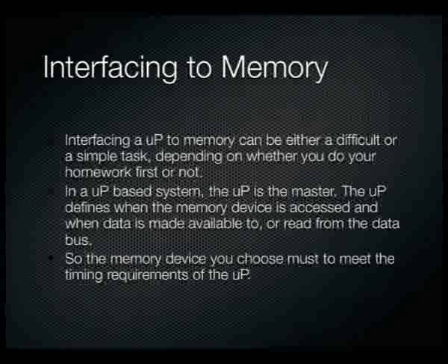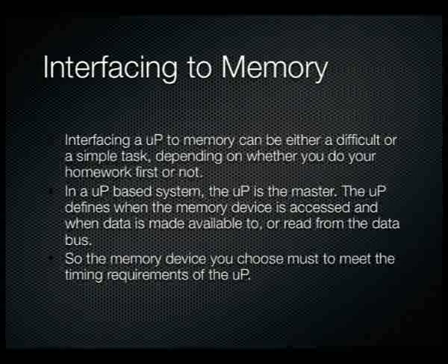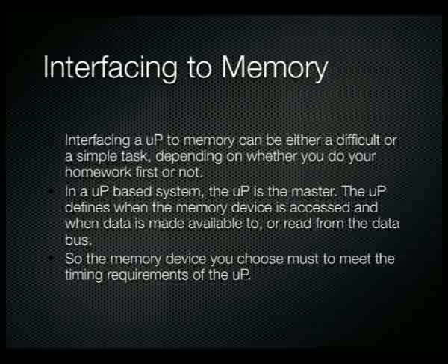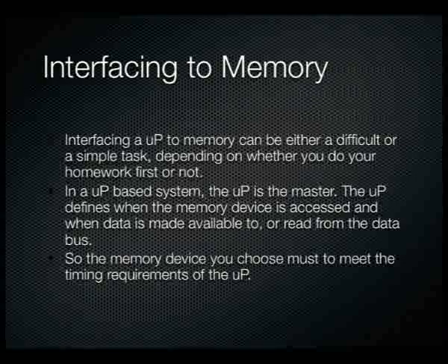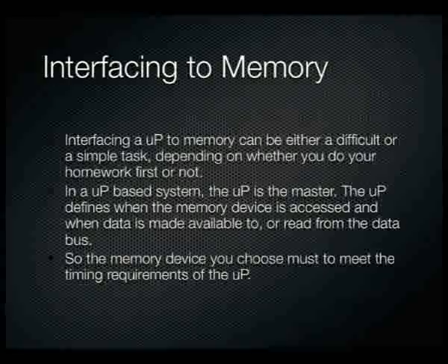So if that memory device you've chosen can't provide the data within that short window of opportunity, then it's an absolutely useless component and you shouldn't use it. So it pays to do your homework first. If you can find devices that will talk to your microprocessor in the appropriate time, then you'll make your life a hell of a lot easier. So the microprocessor will define the timing for the other components. So you need to pick components that meet the requirements of the microprocessor.